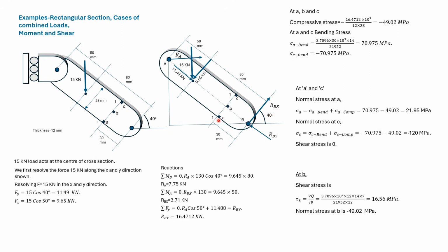RBx into this distance gives the moment, and we find the tensile stress at A and the compressive stress due to bending at C.